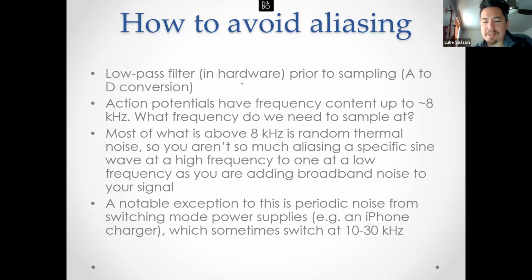But the problem is when you're doing electrophysiological recordings, where you're recording these microvolt signals, then anything is going to be a huge artifact. Certainly going to be more than microvolts. So the way that these people at Janelia fix this, remember I was saying that we have high pass and low pass filters on our amplifiers at somewhere around 8 kilohertz. So what they do is pass current through the animal, but at a frequency of about 1 megahertz. So it's a super high frequency oscillating current that passes from the lick spout into the animal and back through the ground electrode. But the frequency is so high that it's all filtered out by the low pass filters on the acquisition software.